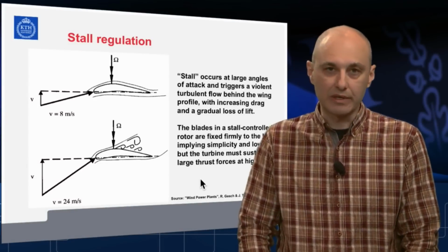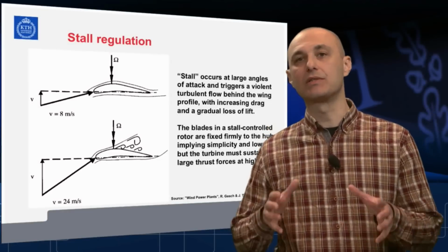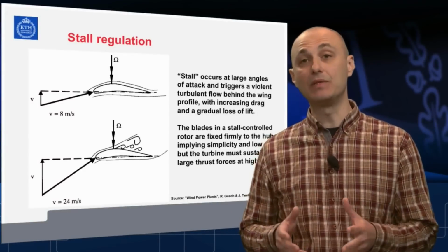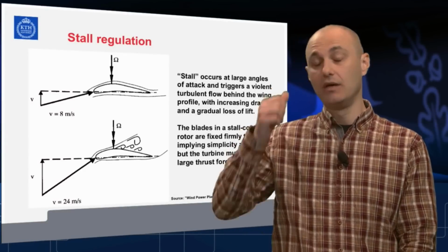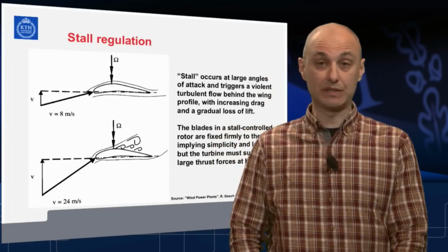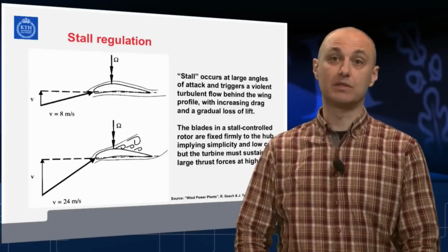How can stall work at all? It actually works only for turbines directly connected to the grid. These are the simplest, the most robust machines, which primarily used simple induction generators in the early days of wind turbine technology.